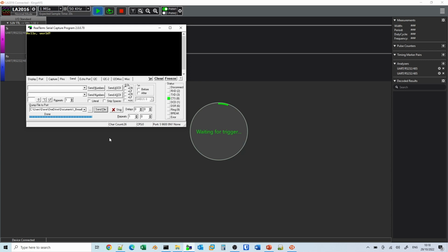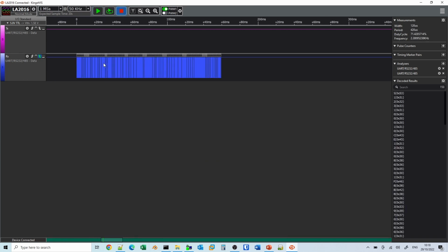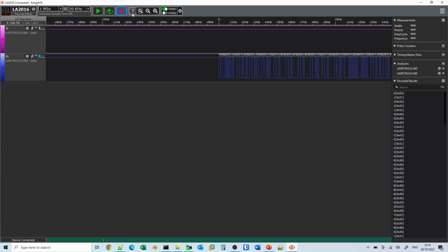All we're going to do now is put the NanoComp in load mode and send the file, and we can see it sampling. We can end the sample because we know we've got all the data there. If we zoom into the data here, we can see that the serial data has been decoded, and we've got 53, which is S, 3132, so that's S123, which is the length, 1000, and 10CE 120. So that's what we expect. That's working okay.